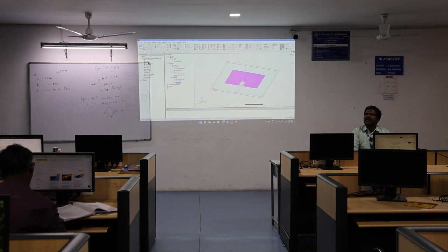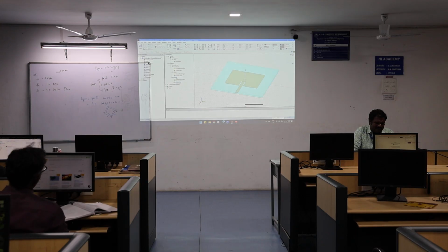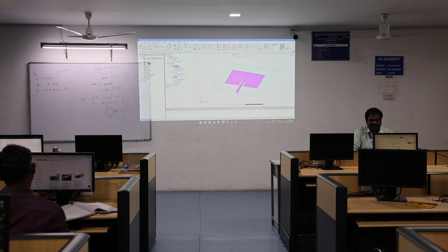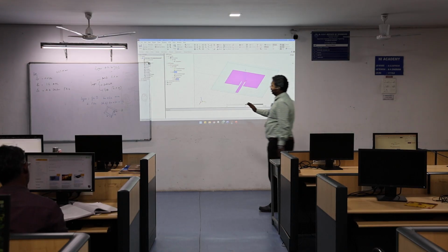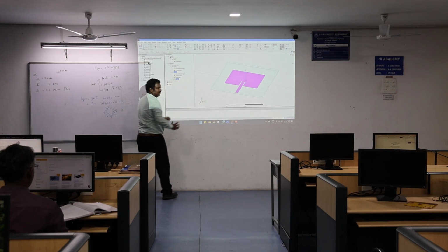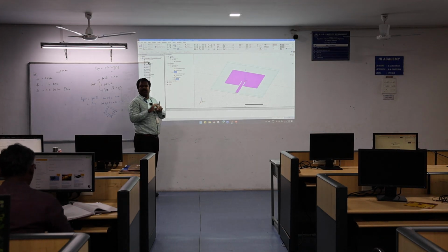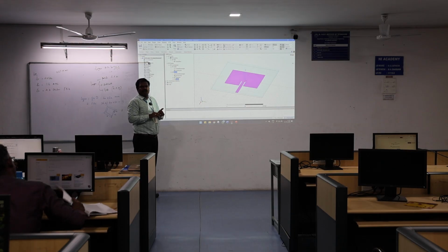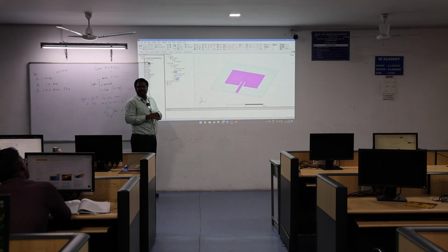So this is the way we connect feed line 1 and the patch. Here the patch and feed line use the other Boolean operator, unite. When you click on unite, both structures are joined together. So you can see all the operations in this model analyzing tool. Everything you click on, insert the plane, the values we change, all that information is notified in this toolbox.